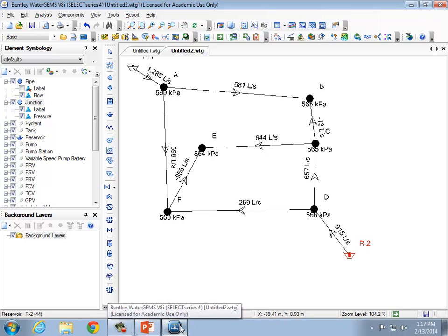One more question. Sure, yeah. How were you getting the WaterGEMS to accept flow out from the reservoir? No, it naturally takes flow out from the reservoir. So you just put your elevation in and we can run it? That's right, yeah. As soon as you define the elevation of the water, then that's where the water will come from if there's an outflow that's defined.